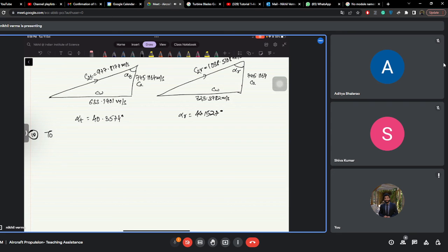Okay, so now we know that the stagnation temperature after the nozzle is constant at the tip and in the rotor. So you can calculate, this is some C2. Let us call it for tip. So T2 is 900 minus 977.8174 squared by 2 into 1147.